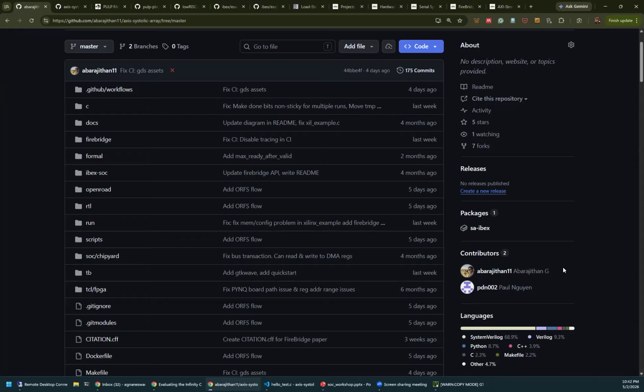If you are reporting numbers, doing it from the Linux level is way more interesting. But you also have to remember that once you go from RTL level to SoC level to Linux level, your measured performance is going to go down, because you have more data movement overhead. If you are publishing, you can report that on RTL level we are getting this much, on bare metal this much, and on Linux that much. That will be very interesting.